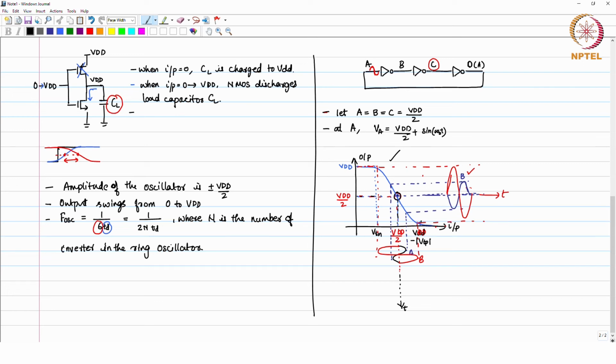Okay. It is not that it is working only for this; with some other phenomenon, it is the same thing. So, what is the same thing? The gain across the loop. It will start building up the oscillations when the gain across the loop is sufficient and the phase which you are adding up is equal to 360 degree.